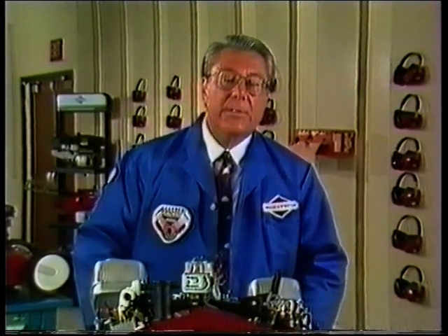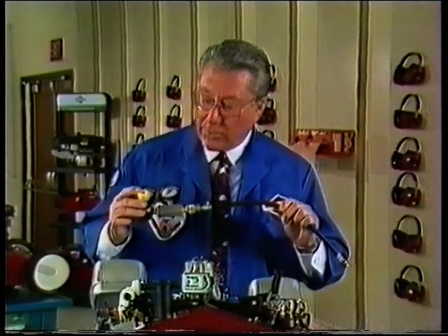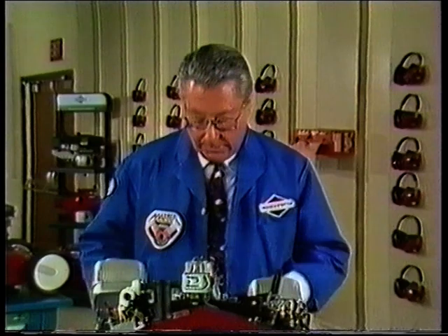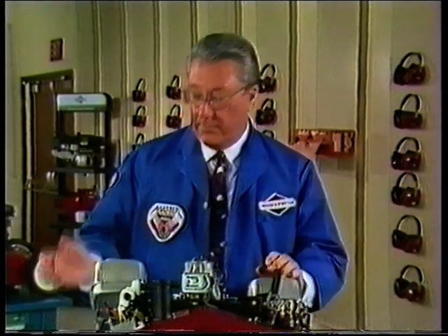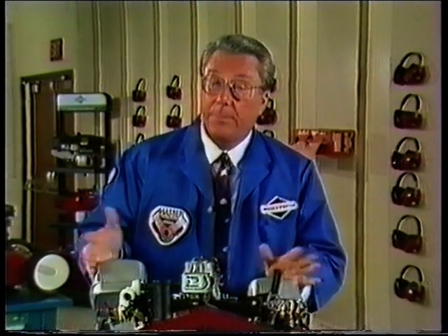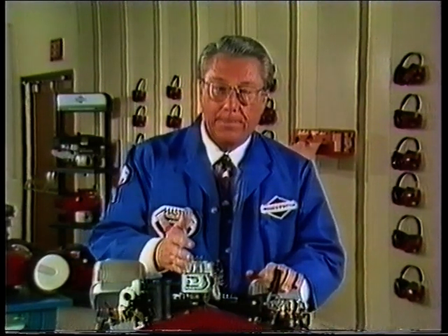Before you conduct these procedures, you need to first test the ignition system with a spark tester and the engine compression components with a leak down tester. Let's assume that we've already tested the ignition and the compression. These appear to be okay. So, our next step is to begin testing the carburation system.